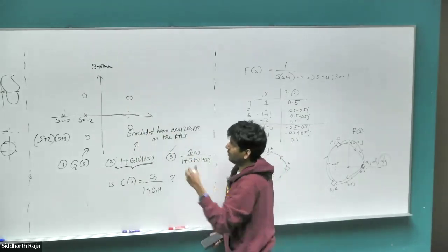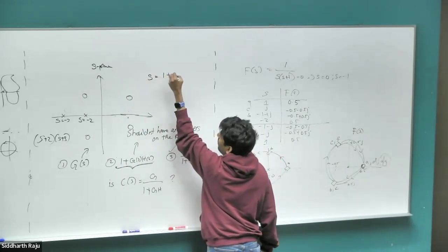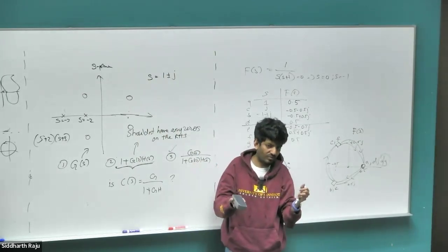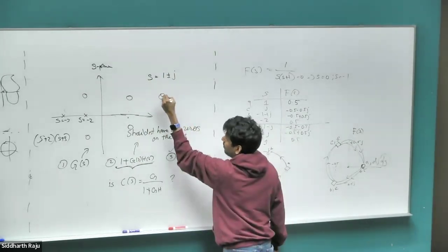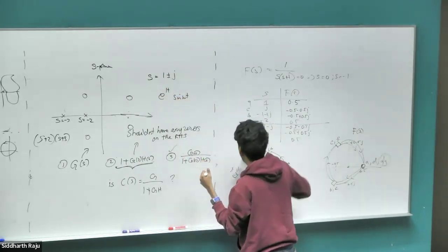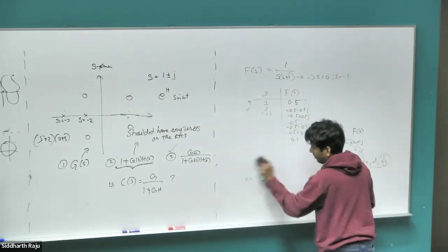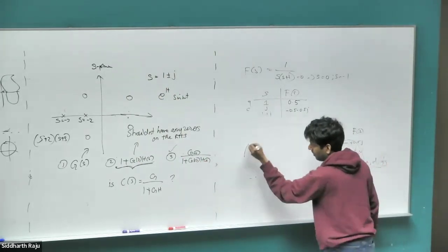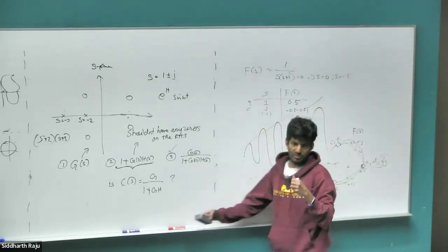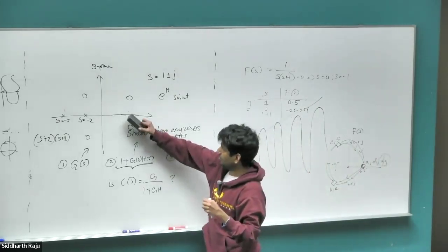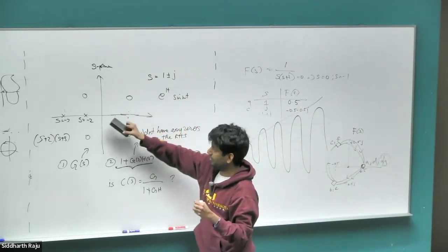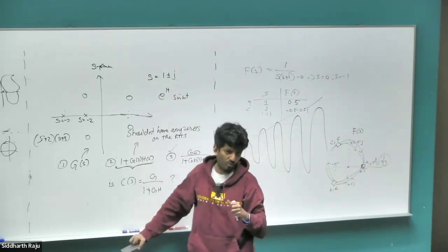Right, because you would end up with a term s equal to say 1 plus or minus j. The plus or minus j term would end up coming out as cos and sine components. This one term would still end up being e power 1t times sine omega t, right? When you take the Laplace inverse. And the time response for that, instead of being a nice exponent that we would expect, would be a sinusoidally, exponentially growing signal. It doesn't help for stability either. It doesn't matter if it's on the x-axis or if it's above. Anywhere on the RHS, if there is a real component, only the real component matters. If there's a real component anywhere on the RHS, that would blow up the whole system.